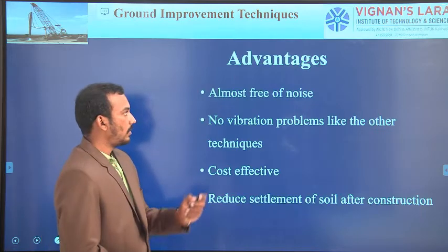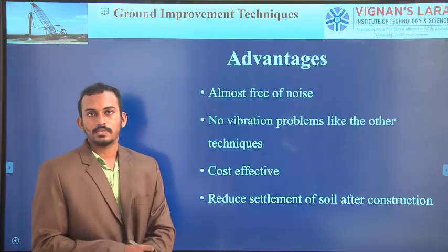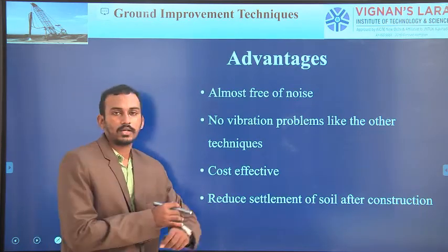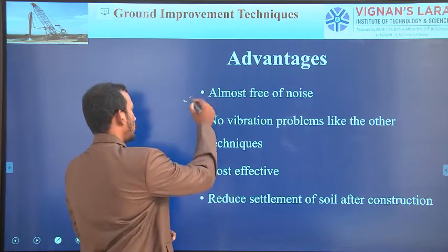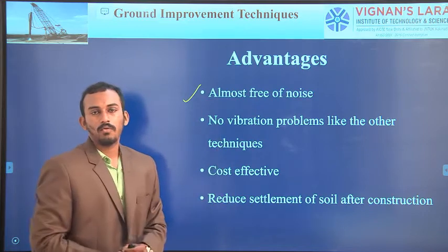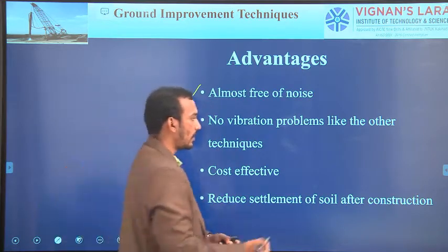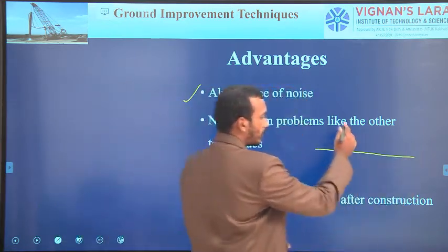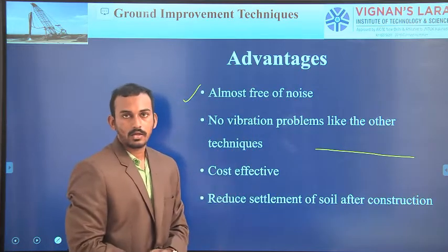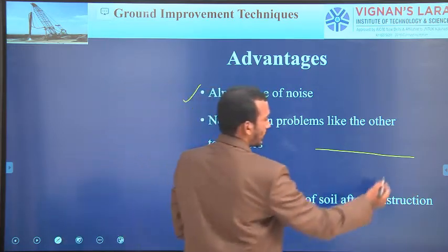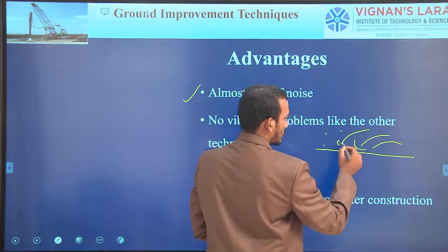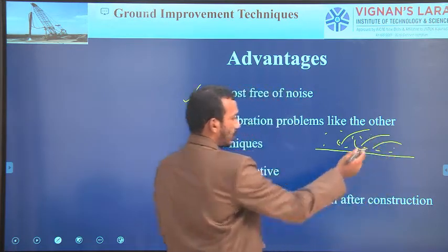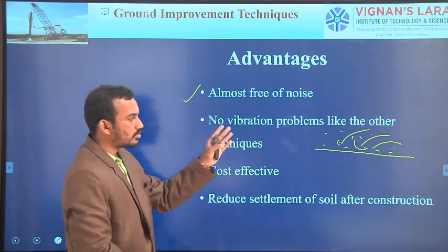The next one is coming to the advantages. So what are the various advantages of using this preloading technique? The first one is almost free of noise. This is the available site for us. We are going to construct a building on the soil. What we are doing is just placing some excess amount of soil. We are not creating any noise. So it is almost noise free.